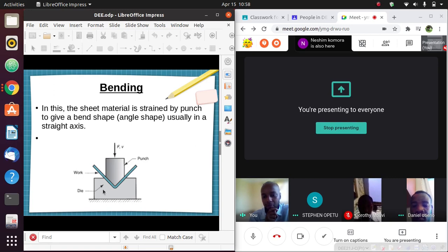The most important parts in a bending operation are these 3 points, these contact points, here, here and here. And depending on my punch or the shape of my die, I can make my bend of cylindrical nature, or I can make my bend rectangular or square. So that will depend on the shape of my ram or punch.